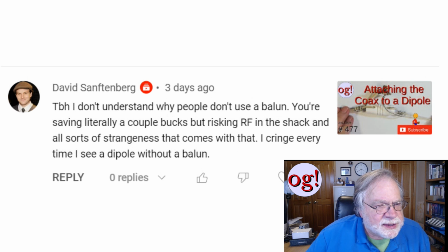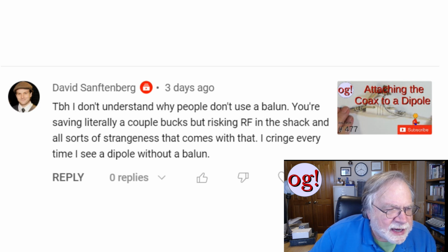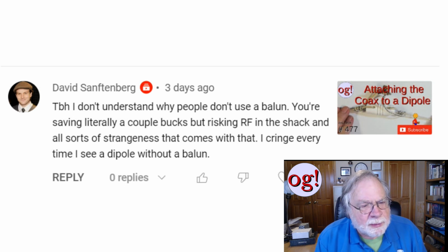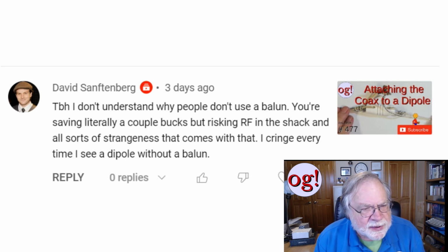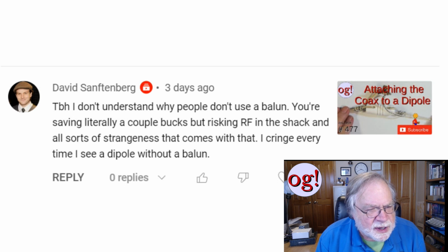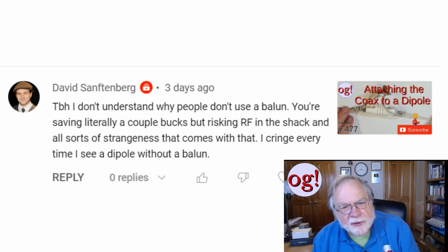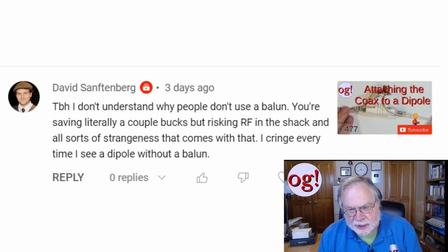Okay, David Sandfenberg, TBH. I'm not sure what that means. I don't understand why people don't use a Balun. You're saving literally a couple bucks, actually close to 100, but risking RF in the shack and all sorts of strangeness that comes with that. I cringe every time I see a dipole without a Balun. I tell people, if you have RF in the shack, by all means, go put in a Balun.